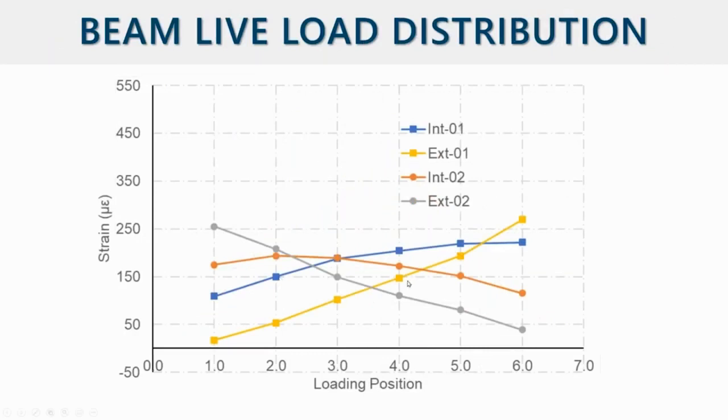We also moved the truck transversely and plotted all the data, and this data can be used to calculate the actual distribution factor, the live load distribution factor, on the steel beams.